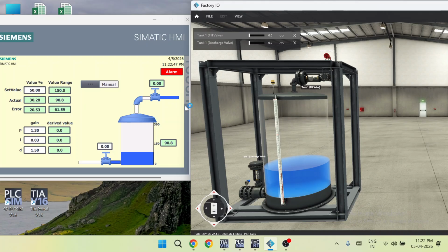In this, there is a tank. Its value will be available from 0 to 10. Here is the filling valve and this is the drain valve. They will be analog type, so the value will be 0 to 10 for both of them, and there is a level sensor. Its value will also be in the 0 to 10 volt range.